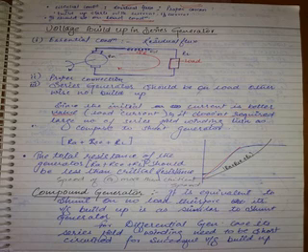So let us consider the series generator has some load connected. Loading means automatically the current is flowing in the machine. So let us consider you are starting the machine with some load, as the machine is loaded. When the machine is loaded, automatically what flows in the load? Load current IL. So from where is this current coming? It is coming into the field winding from the armature. So IA, ISC, all are the same. So when you connect the load, it is demanding current from the armature. It is drawing current from the armature. The current will flow through the field winding, and automatically as the current increases, flux will increase and automatically voltage will increase. Is the point clear?